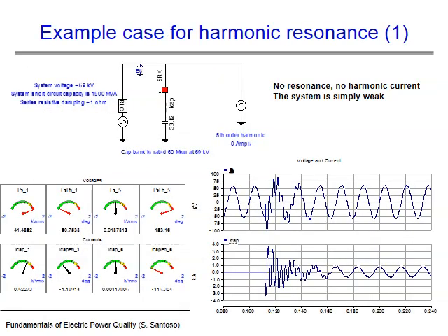Here is a model made in PSCAD simulating an energizing operation of a shunt capacitor bank on a power system. The Thevenin equivalent of the upstream system is a 69 kV voltage source with an inductive reactance and 1 ohm series resistance. In this case, there is no harmonic current being injected into the system. At time 0.11 seconds, the circuit breaker to the 60 megavar capacitor bank is closed, energizing the bank. There is a transient response to the energizing event, which is damped out after 2 or 3 cycles due to the resistance.